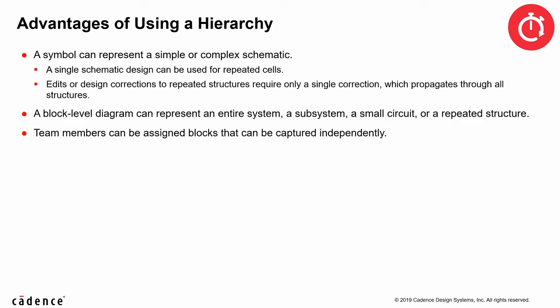So, to overcome the limitations of a flat schematic, you create symbols for your schematic diagrams and use them to create a hierarchical design. So, what are some of the advantages of using a hierarchy? Now a symbol can represent a simple or complex schematic. A single schematic design can be used for repeated cells. Edits or design corrections to repeated structures require only a single correction, which propagates through all the structures.